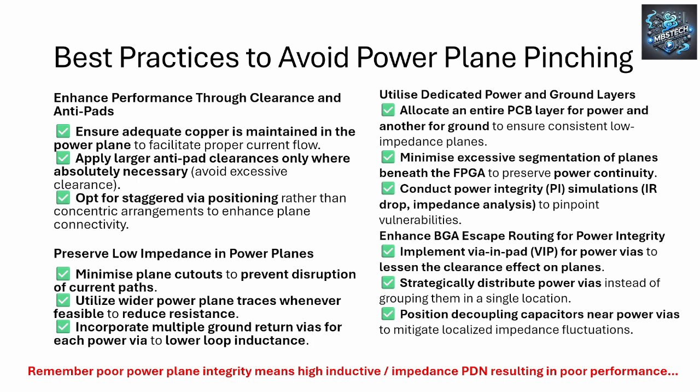If whatever the decoupling is connected to is degraded from an impedance point of view, like in power plane pinching, it's going to have a degradation effect on your PDN. Doesn't matter how much decoupling you put in. Okay.